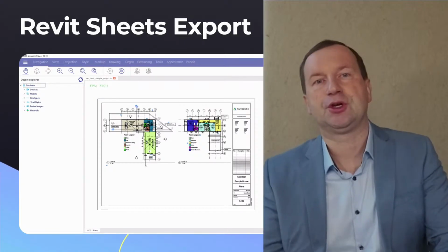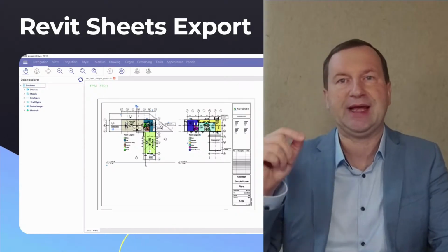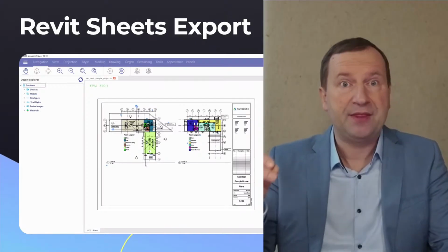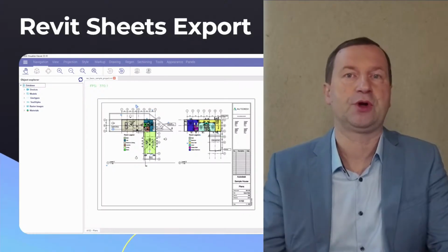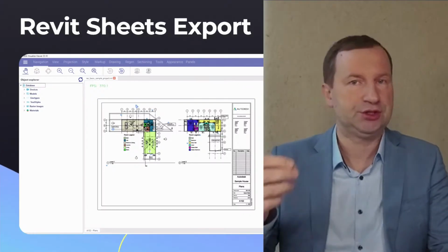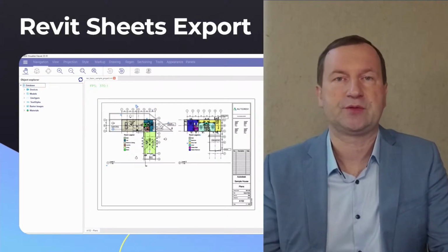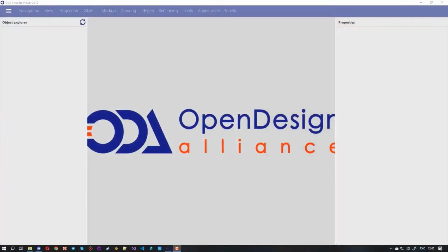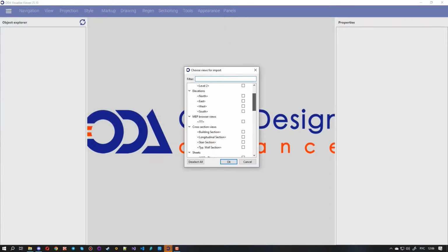The second challenge was that in Revit, most geometries are represented as 3D objects, even in sheets. Therefore, during export to DWG, these must be converted to 2D objects, requiring additional functionality to handle the 2D projection for these transformations. It also was noted that in this two-step process, the final result depends on the outcome of the first step, the import from Revit into Visualize.